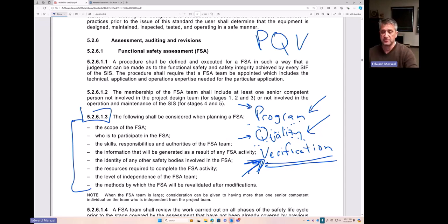If you're doing a functional safety assessment and when you're looking at the risk analysis, you see that the project team used a risk graph to pick SIL targets. Now, there's nothing inherently wrong about using a risk graph. But from a functional safety assessment, the project did not follow the program. So you have to punch it out and say that your program is X, what you did is Y. These two things are incompatible, so you're going to need to resolve that issue.